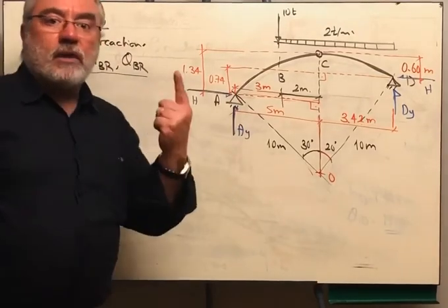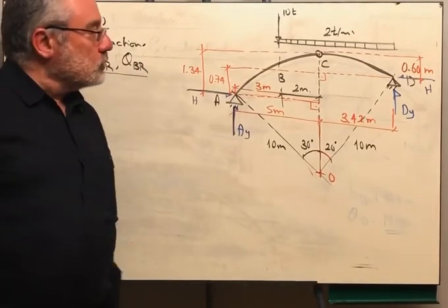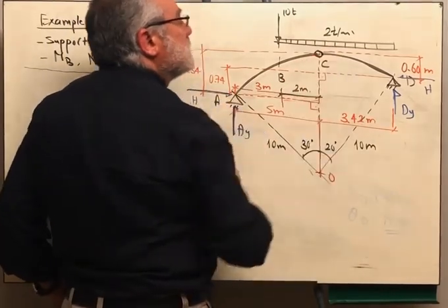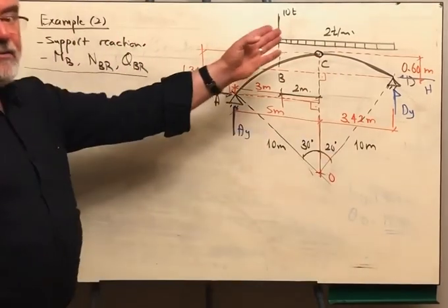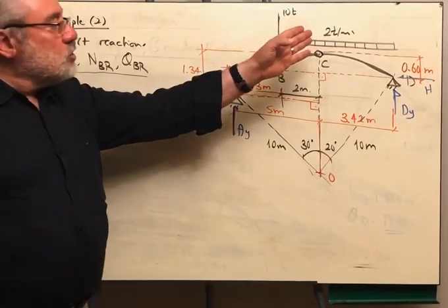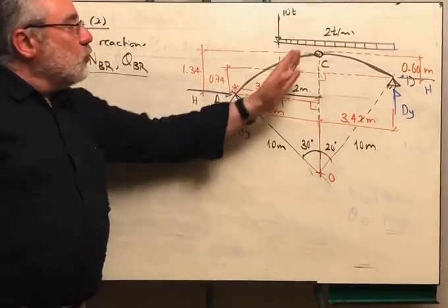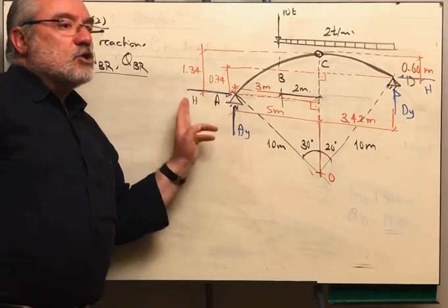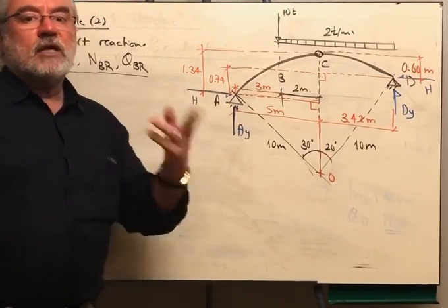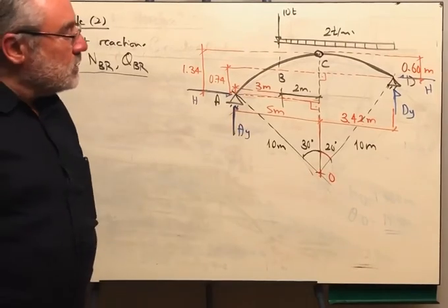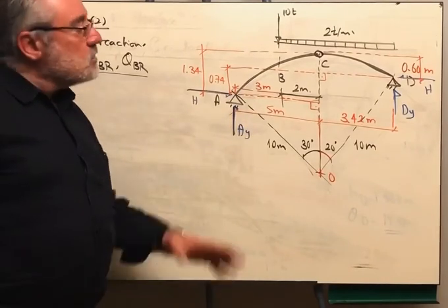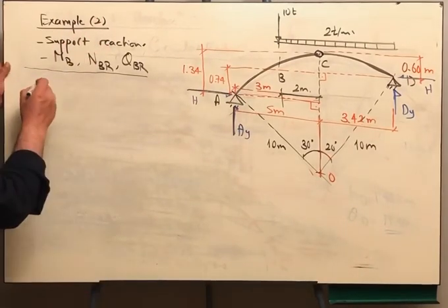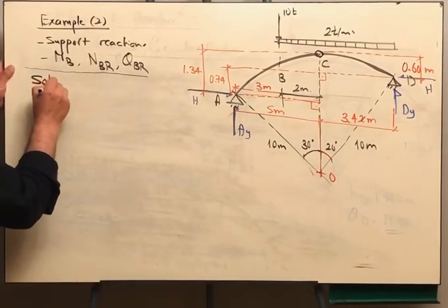Then you are having one equation and two unknowns. You will have to select moments about point C as well, because this is an intermediate hinge. Without this condition, I couldn't have solved the problem. We can take the left part, then we are getting another equation in the same two unknowns. Then we can solve two equations, two unknowns simultaneously to get the support reactions, and we'll proceed identical to what we solved before. So let us have the solution.